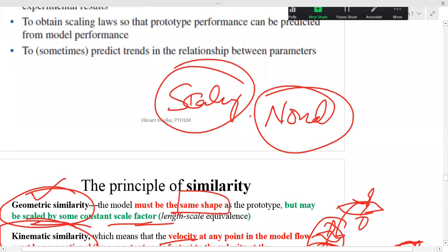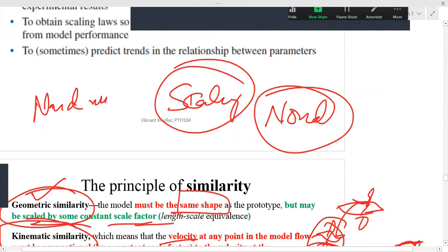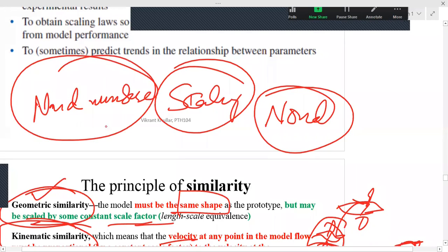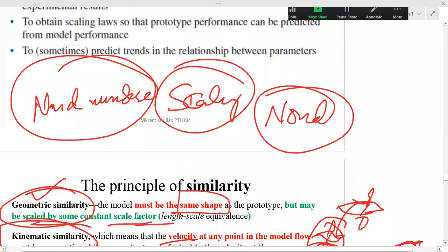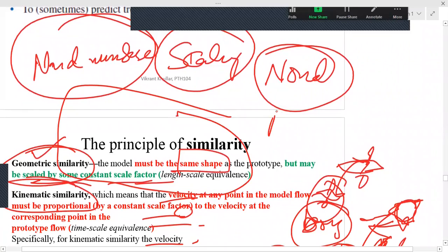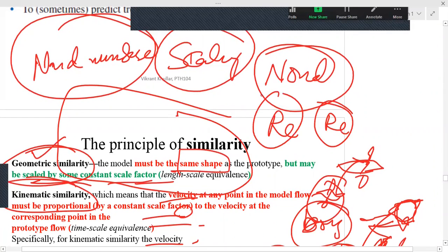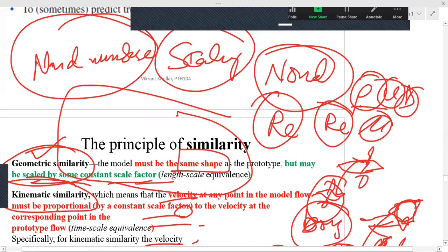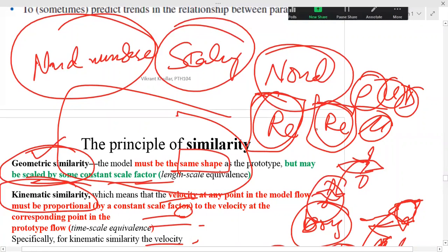And non-dimensionalization of the equation actually leads to certain non-dimensional numbers. And these numbers are important because they help us to build these similarity concepts so that you can actually compare Reynolds number only instead of comparing rho, v, d, mu and each and every variable separately. So you are reducing the number of variables you are studying. So that is the utility of non-dimensionalized numbers.